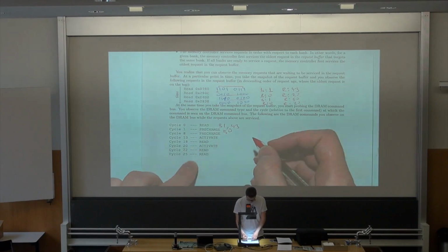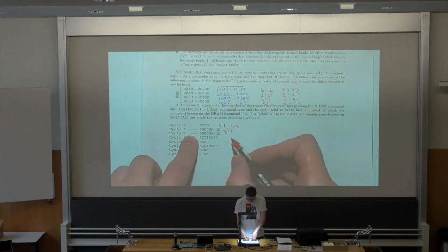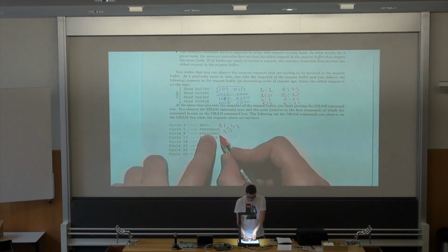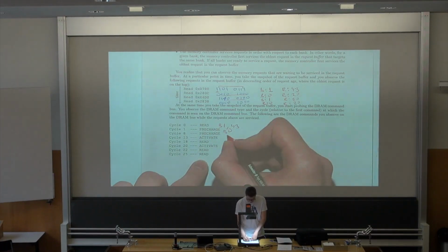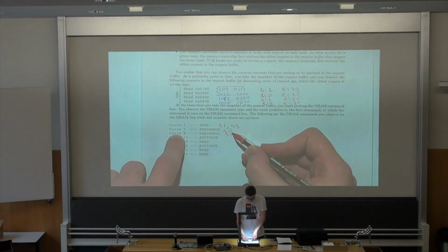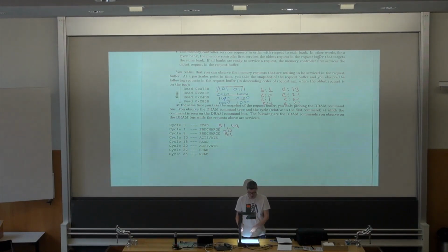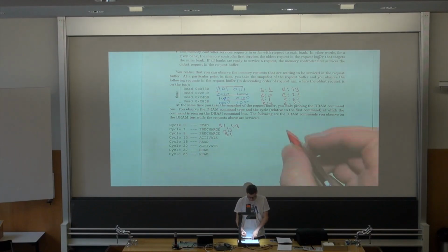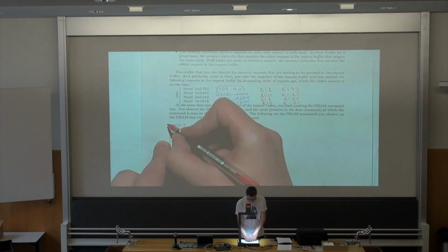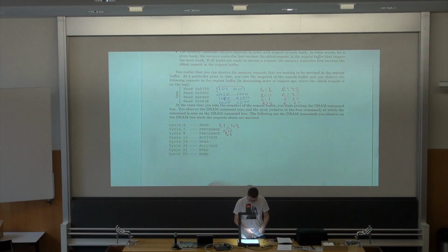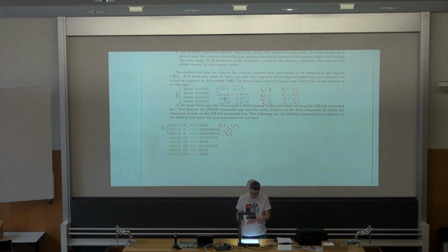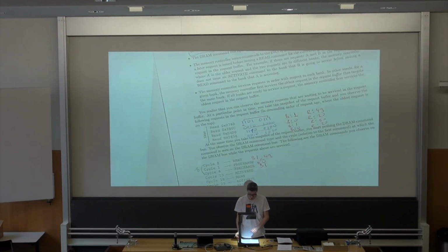Okay, so if we continue here, we can figure out more information. For example, here at cycle 8, we get a precharge command, right? We already precharged bank 0, so this is guaranteed to be bank 1, right? And since this is bank 1, and we waited for exactly 8 cycles here to issue a precharge, we know that the timing parameter here between read to precharge is 8, right? So this here, let me use a different color. So this is 8 here. So yeah, read to precharge latency is 8 cycles.